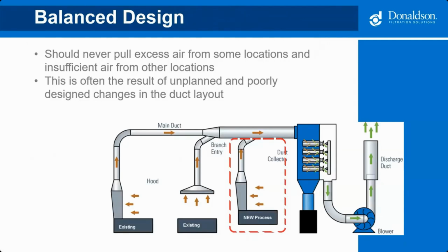As I mentioned earlier, having an unbalanced system can also create duct design issues. When customers add new equipment to an existing system, they often don't consider the impact it has on the existing filtration system. In most cases, existing systems aren't modified to accommodate the additional airflow or static needs, and thus it becomes unbalanced. It's lucky if you know a customer is going to expand their process on the front end. That way, you don't have to sacrifice performance if they add equipment later on.